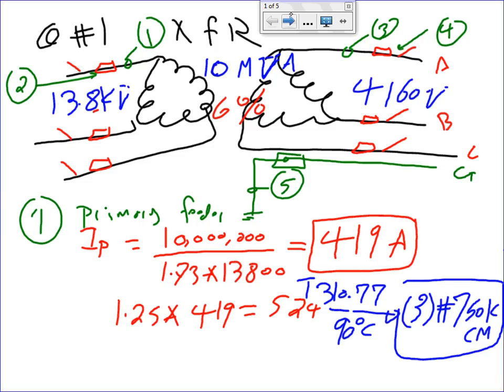Meaning, if I short these together, see what I did? Right in here, right at the transformer terminal. You only do that one for testing, which is the worst scenario. That's kind of the doomsday. If you do it this way, you bond the three together under one line.